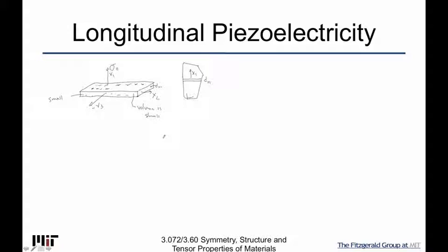So by cutting a very thin slice and understanding piezoelectricity and the volume dipole effects and surface effects, I've set it up so I could pretty much measure D11, and all of the other charge that's accumulated is very small in comparison, because I've made these huge surfaces in the direction that I care about. And again, this is because it's a piezoelectric, and I've recognized that this is a way I can map this out.